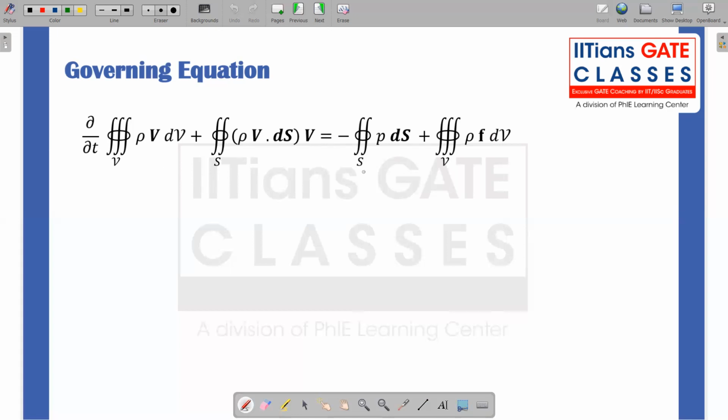So the pressure one is slightly straightforward, because here I cannot use the Gauss divergence theorem. Instead, I can use a corollary, that means a special form of the Gauss theorem that relates to a scalar field. So I can use the gradient theorem. Using the gradient theorem, I can write this particular part as the volume integral of the gradient of the pressure field times dV. Fine. So this is straightforward.